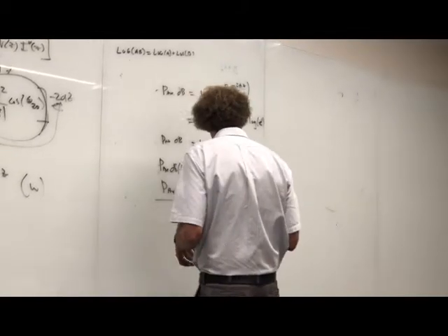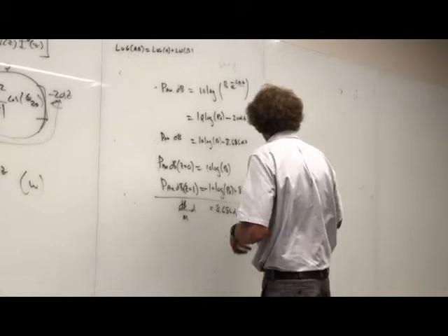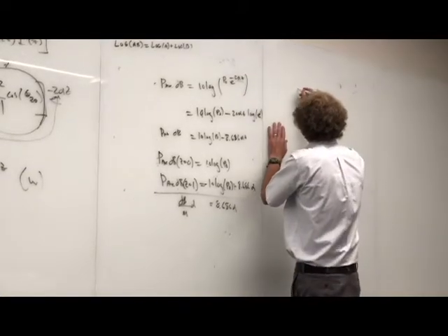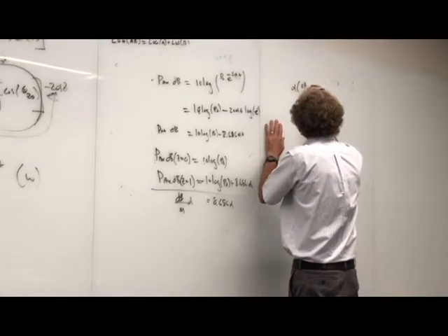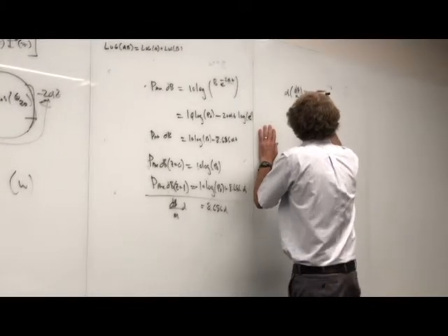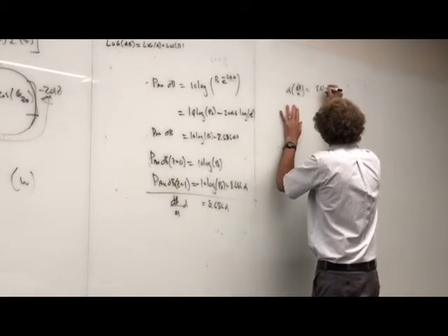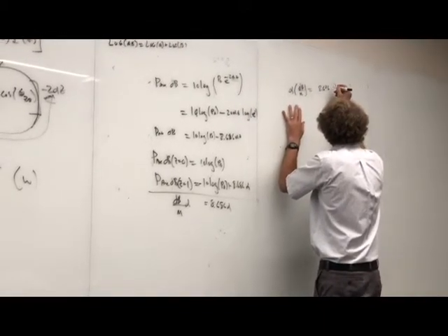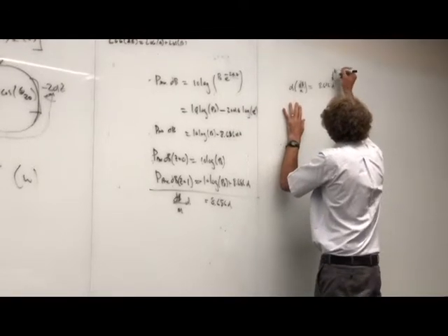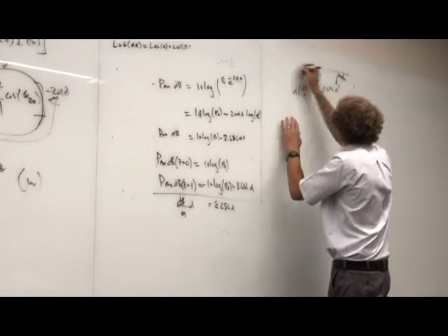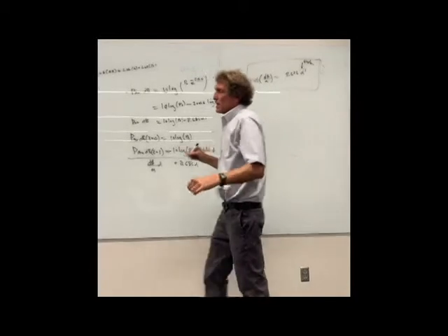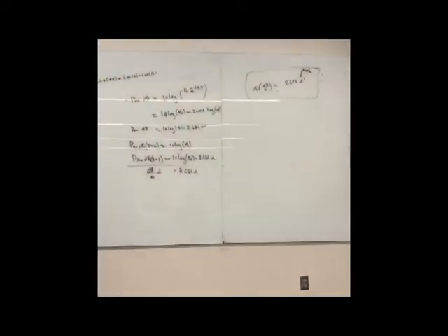Alpha in dB per meter. And this is important. If you want alpha in terms of the decibel loss per meter, you take 8.686 times alpha in here, that's in Nepers per meter. So this is what's called the relationship or translation of one to the other.